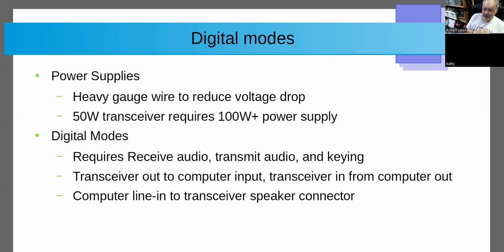Yeah. And most of the modern ones, you can hook up with a USB cable between the computer and the radio, and you get virtual audio channels and keying. You just have to figure out what the correct port is on the computer that your computer is seeing. But if you don't have a radio that can take a USB input, then you actually have to use the physical connections, which used to be RCA type cables.